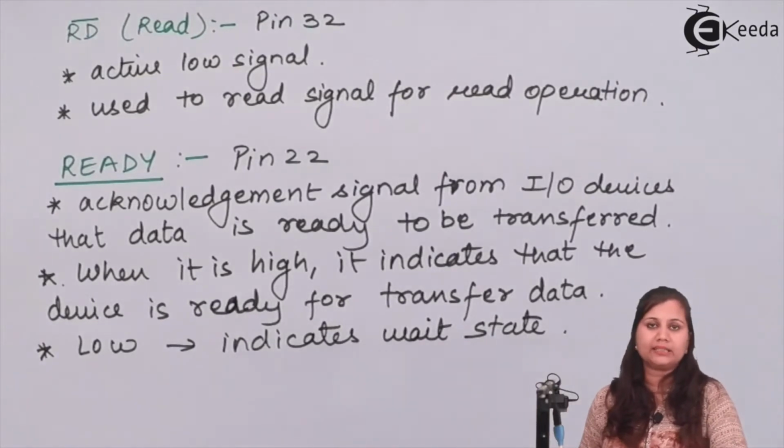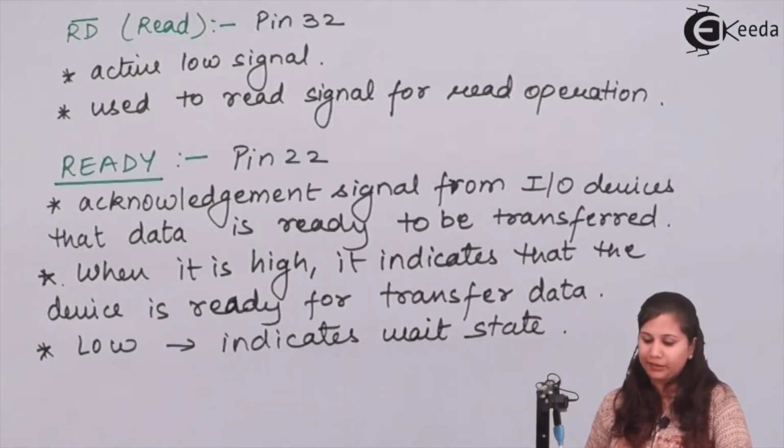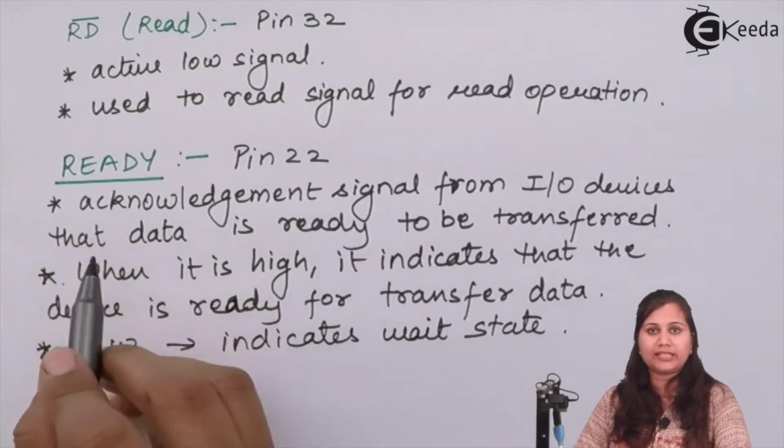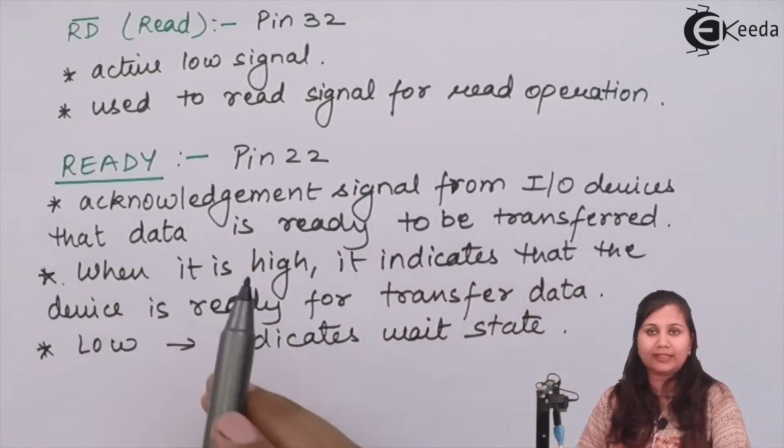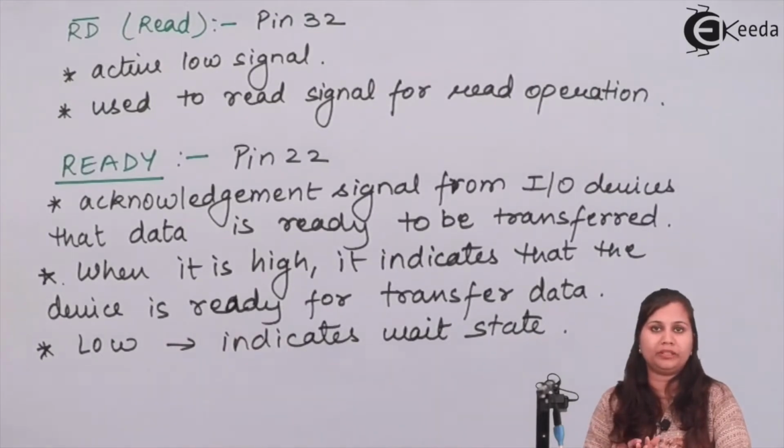It is an active high signal, and we can also say that it is an acknowledgement signal from the input output devices that data is ready to be transferred, meaning the device is ready for communication with the microprocessor.